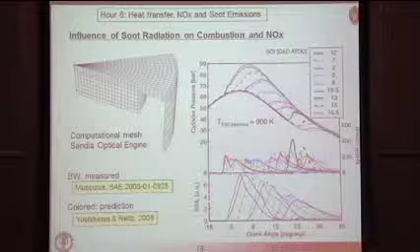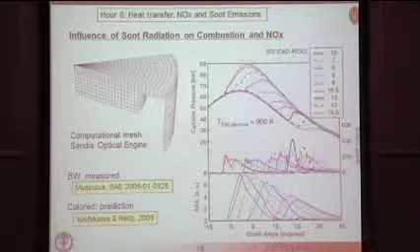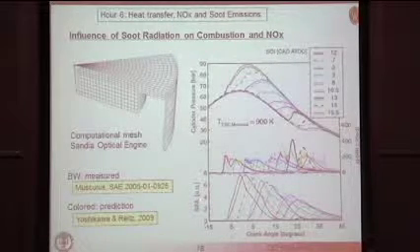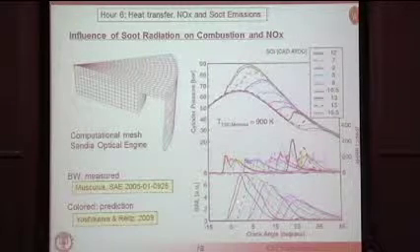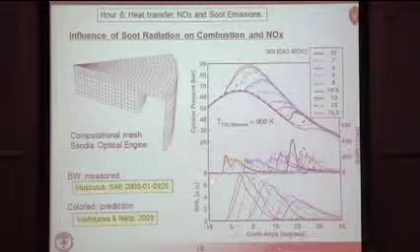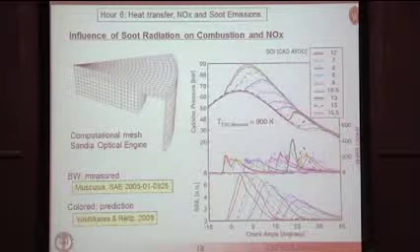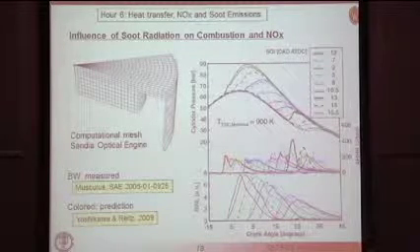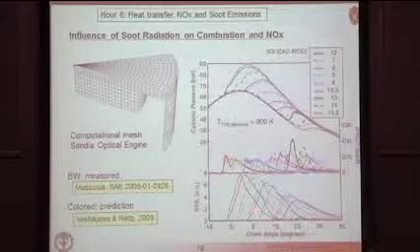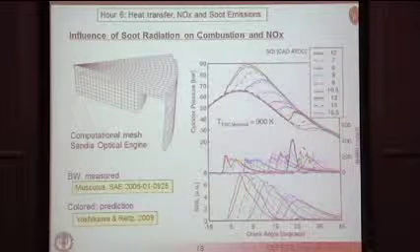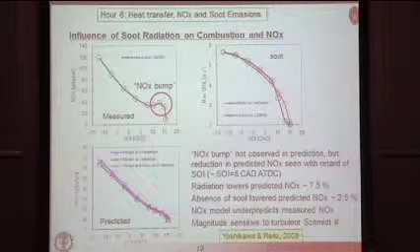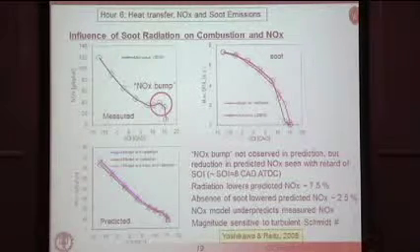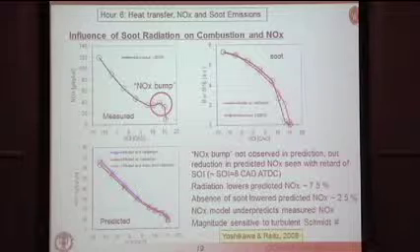We also compared the spatially integrated natural luminosity data obtained from the experiments. Of course, this is in arbitrary units, so we can choose a normalization here. But again, these results agreed quite well with Mark's experiments. So we felt like we were doing a reasonable job with both NOx and soot. And that's kind of shown here.